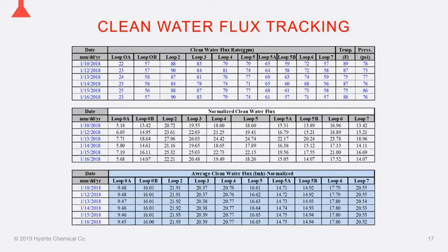So I strongly encourage people to look at the clean water flux trends or this data. A lot of customers today will enter this data and actually have it put into trend line sheets that are much easier to look at. So I encourage people to do that, and that way they can identify problems and correct them before they become a real issue where the plant is faced with a potential shutdown to take their system offline, so we can clean it for 3 days to bring it back to normal.